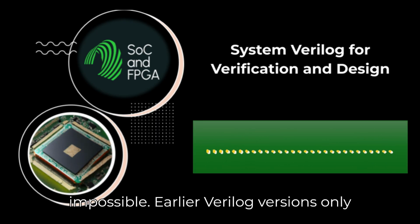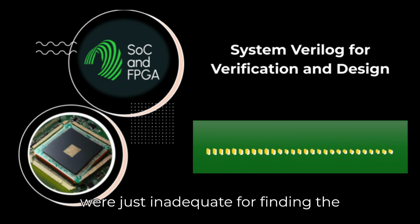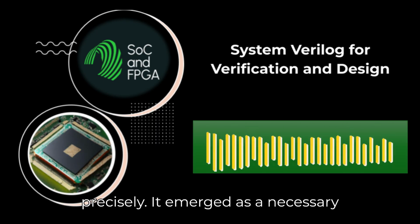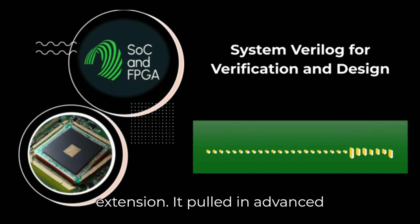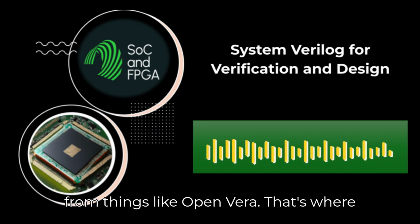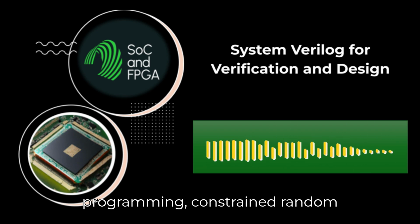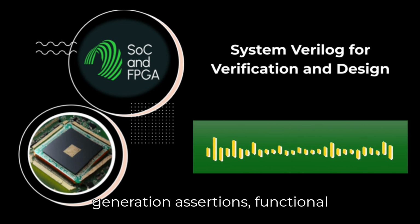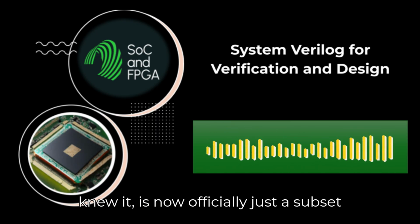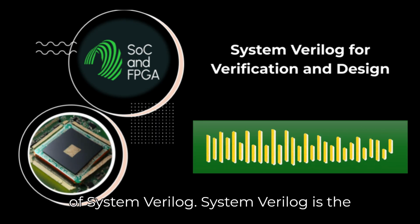Earlier Verilog versions only had pretty basic testing constructs. They were just inadequate for finding the tricky bugs in these really intricate designs. So SystemVerilog had to step up. Precisely. It emerged as a necessary extension. It pulled in advanced verification features, borrowing heavily from things like OpenVera. That's where capabilities like object-oriented programming, constrained random generation, assertions, functional coverage, all that powerful stuff came in. And Verilog itself? Verilog, as we knew it, is now officially just a subset of SystemVerilog. SystemVerilog is the superset.